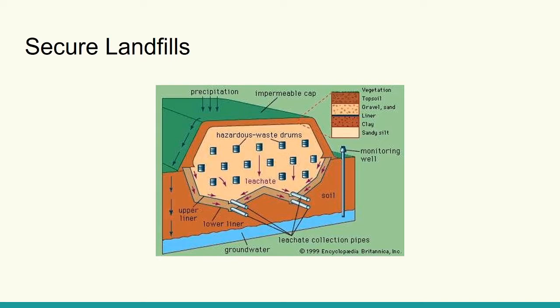Secure landfills are landfills for hazardous solids and containerized waste. It is recommended that hazardous waste must have secure landfills so that it will not spread and affect the community. The secure landfill should have at least 10 feet or 3 meters of separation between the bottom of the landfill and the underlying bedrock or the groundwater table.